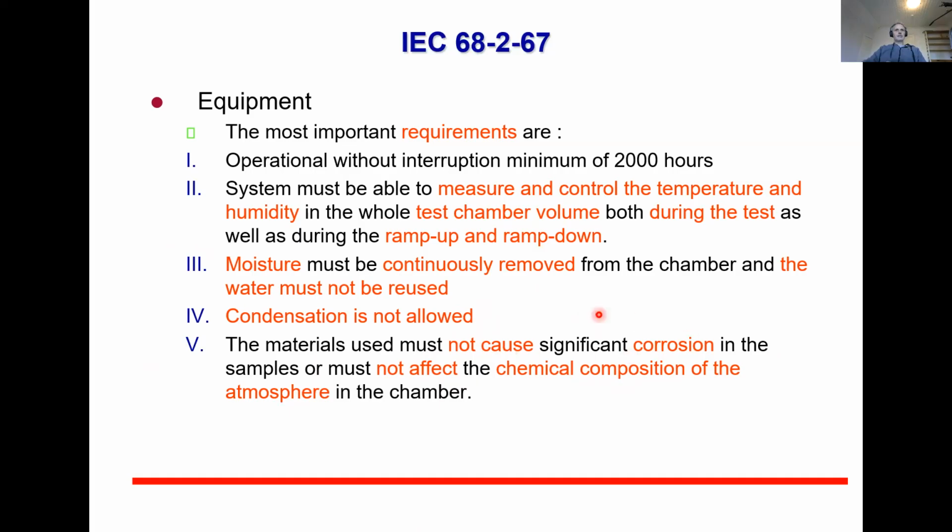Again, no significant corrosion, and these samples may not release any chemicals which would change the chemical composition. Also, of course, the chamber should not release anything. That's the reason that these kinds of chambers are always stainless steel chambers, so nothing is dissolving from the walls of the chamber, which could also change the testing ambient.